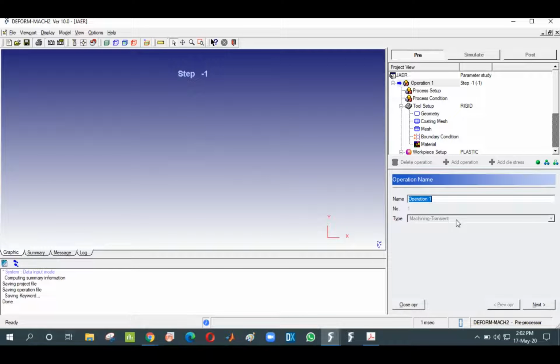After obtaining some subsequent chip formation, we have to make some modifications in the chip, and then convert that into the steady state condition. So initially it will be in the transient condition, and upon modifying the chip, only then do we enter the steady state condition.